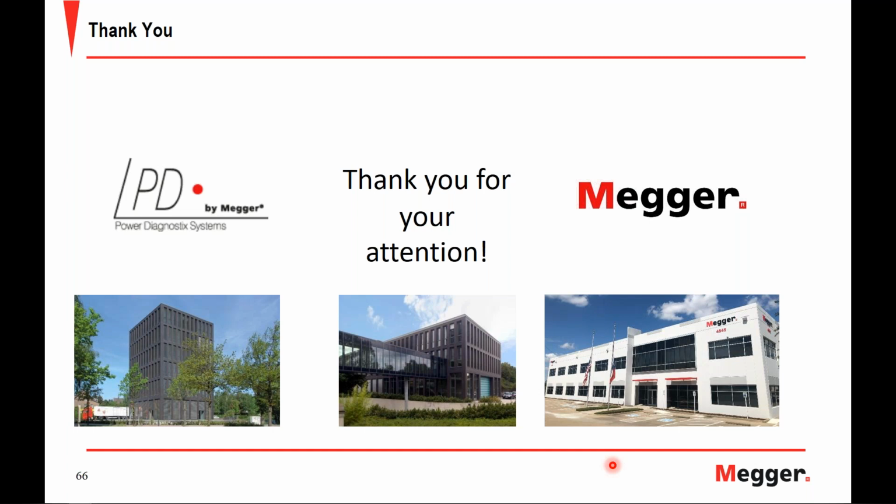So it depends really. The instrument is capable of either. It depends on the measuring bandwidth that you're doing. So the picocoulomb refers to the IEC 60270 calibrated circuit within that bandwidth, so less than 1 megahertz. Once you start to go past that, then you can't strictly follow the IEC 60270 calibration procedure, and therefore you cannot necessarily relate that to a picocoulomb value, and therefore you start to show the result in the millivolt.